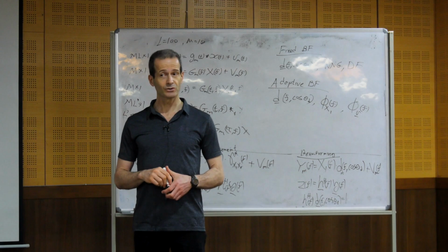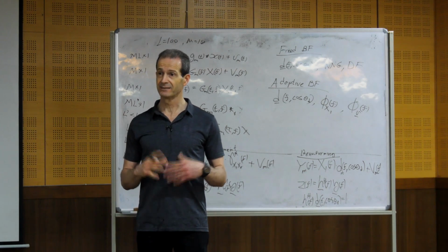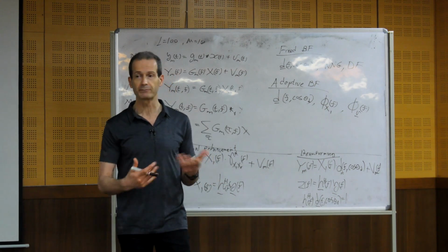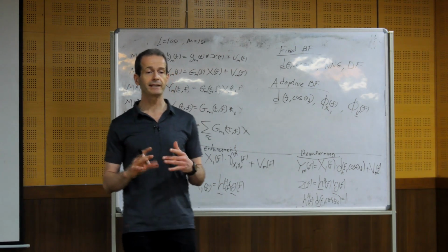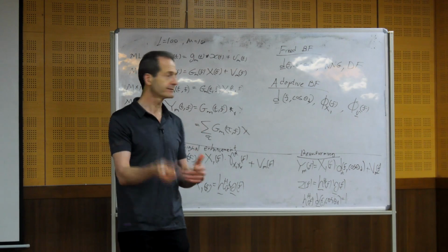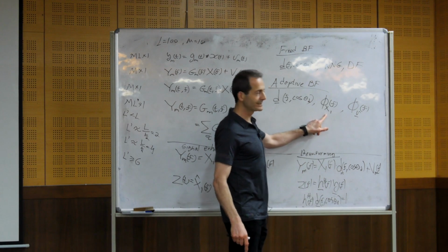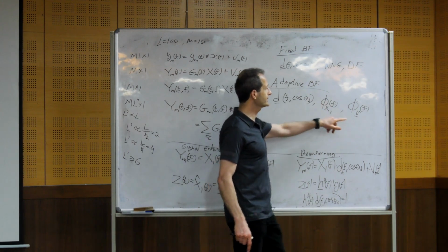Actually, I don't know it exactly. I need to estimate, so I need to track, to follow, to do adaptive. In order to do adaptive beamforming, I always estimate the direction, the variance of the desired source in the reference channel, and the correlation.